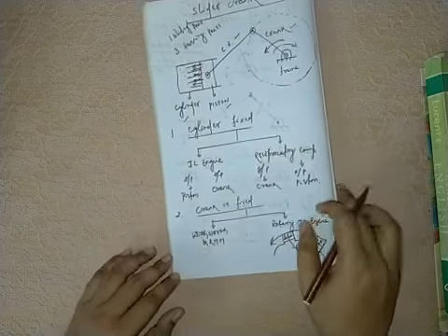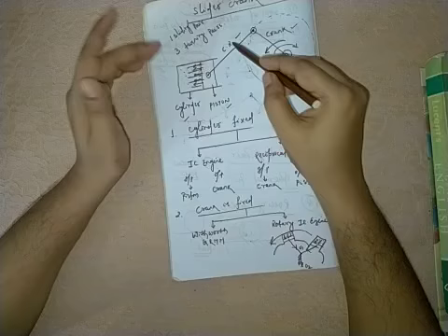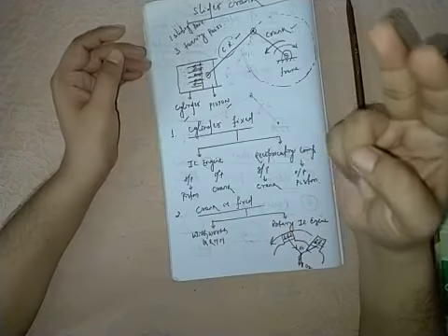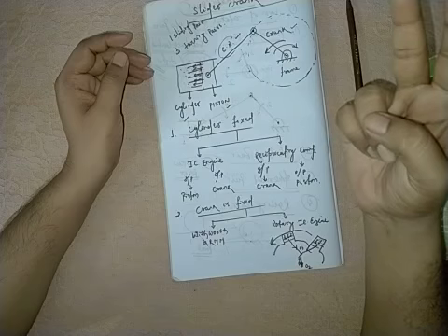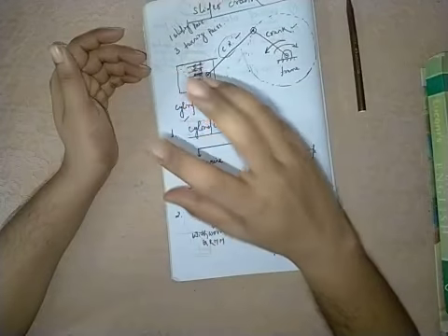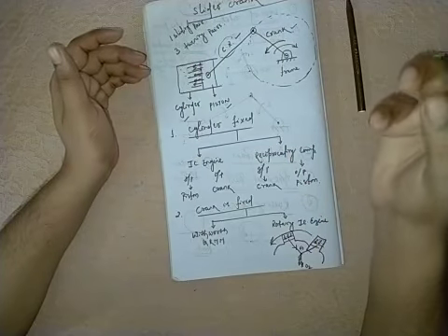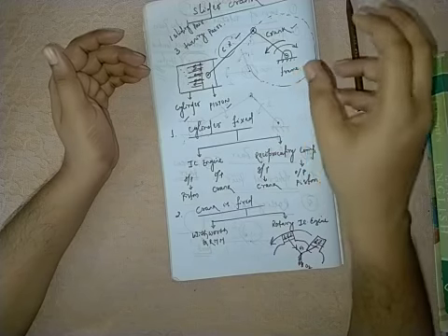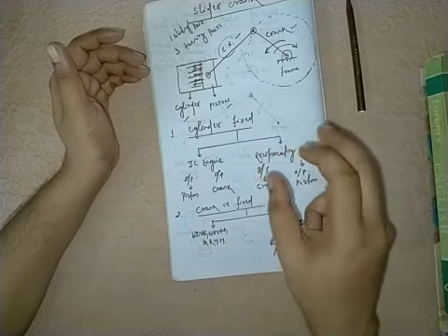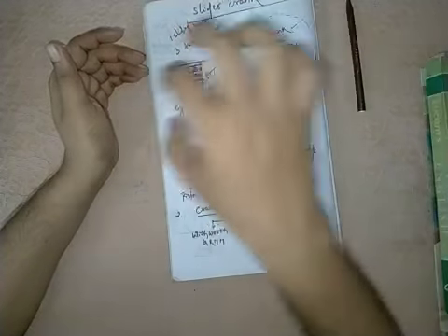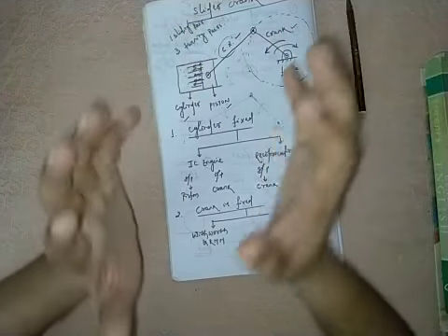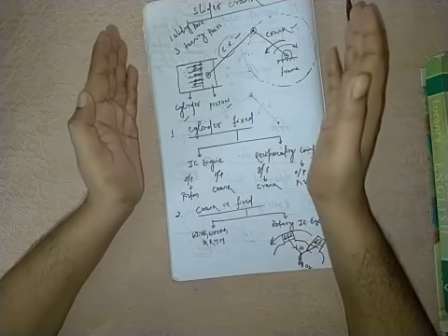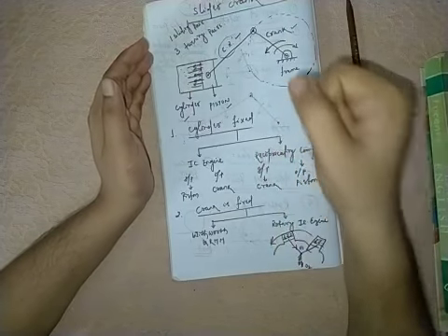Next is when you are fixing the connecting rod. In this case similarly you will get two different machines. One is your oscillating cylinder engine, and another one is the crank and slotted lever quick return motion mechanism. Clear? Similarly, the last one is when the slider is fixed, means when we are fixing the piston. When the slider is fixed, you will get the hand pump or pendulum type pump, means your hand pump.